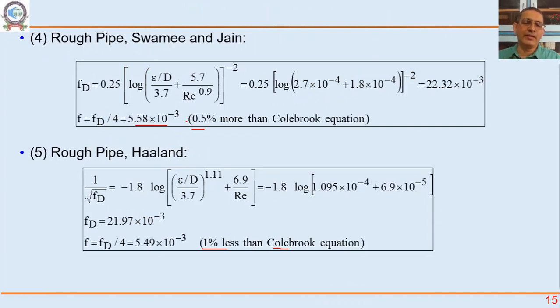So that's the advantage of these charts. We can calculate the friction factor knowing the Reynolds number and knowing how rough the pipe is. We can calculate the friction factor very easily. And now we will try to use this in our calculations.